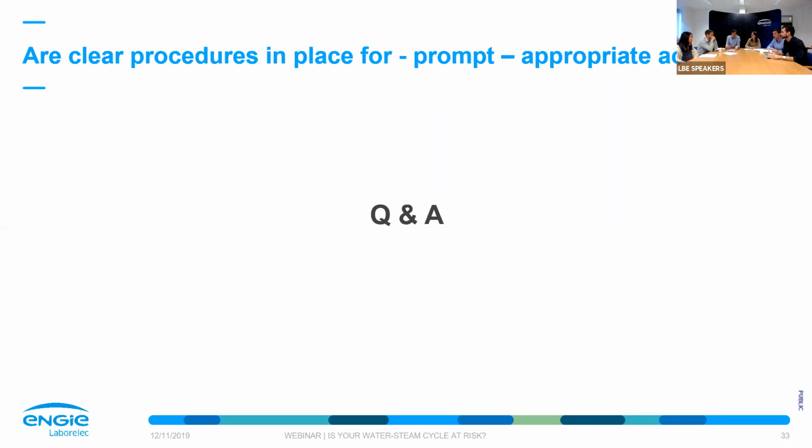Well, yes, the chloride analyzers are not used that often in the power industry because of the reliability and the availability. So it happens very often that you have problems with that kind of ion selective electrode systems. But of course, we are also very interested to know your feedback if there is any on the reliability.